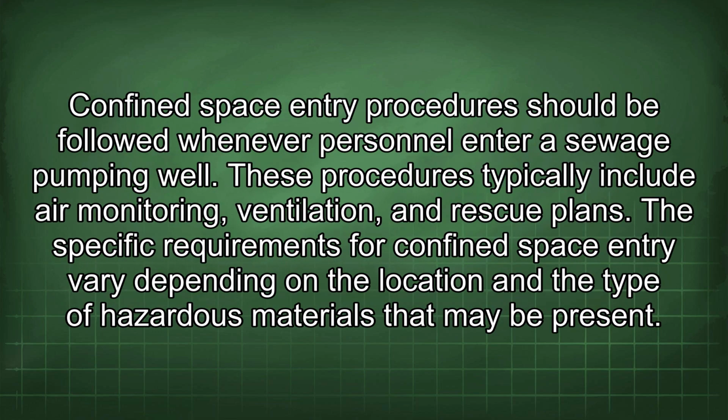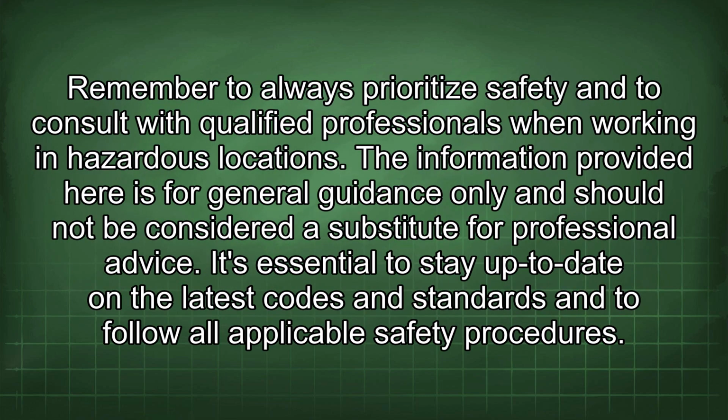Confined space entry procedures should be followed whenever personnel enter a sewage pumping well. These procedures typically include air monitoring, ventilation, and rescue plans. The specific requirements for confined space entry vary depending on the location and the type of hazardous materials that may be present. Remember to always prioritize safety and to consult with qualified professionals when working in hazardous locations.